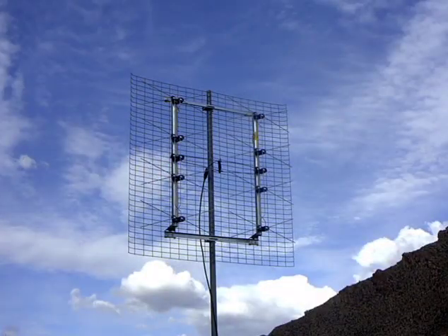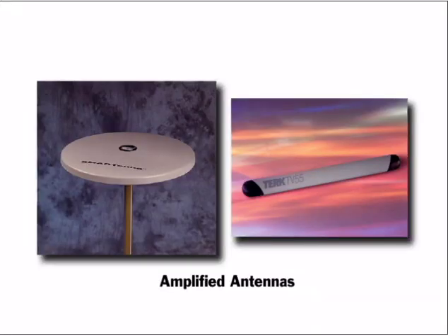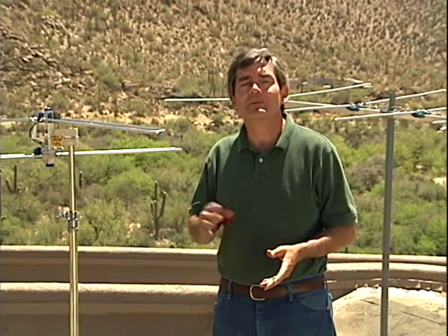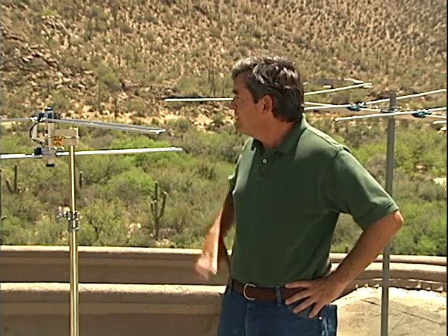In the UHF band, where elements are small, these reflector antennas are excellent at reducing multipath signals from the back and sides of the antenna. While many amplified antennas are available, they shouldn't be needed if you're connecting an antenna to a distribution amplifier. Since FM radio represents an excellent source of music as well as news, FM signals should be integrated with TV off-air signals for distribution. And an outside FM antenna is essential for a good signal-to-noise performance.